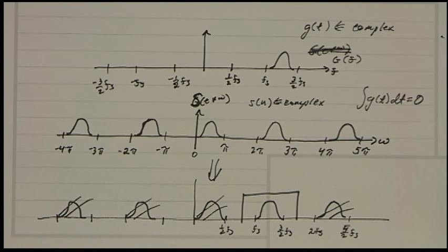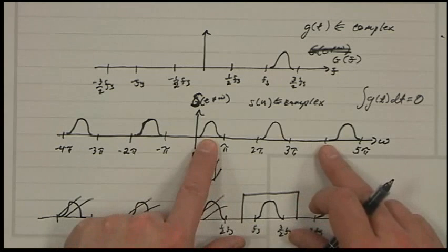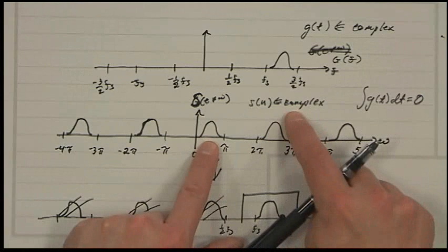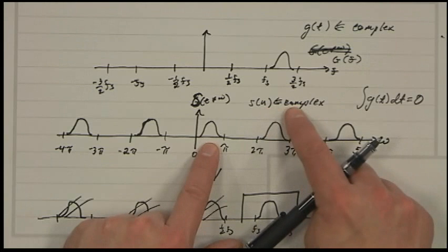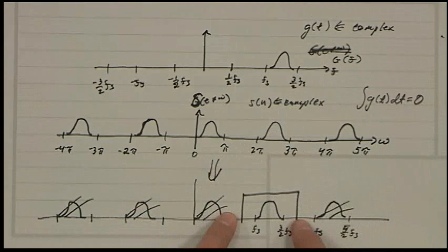In the time domain, that's true. So before I filtered this thing out, when you go to do the reconstruction, what you do is you take the discrete time signal. We're going to talk about this in just a minute. And you use the discrete time signal to modulate a train of impulses. So it looks like a comb. That's exactly what it looks like. But when you filter that signal to remove just this one thing, after that, then it doesn't look like a comb anymore. It looks like basically the signal that the comb envelope traced out. So it puts you back here again.